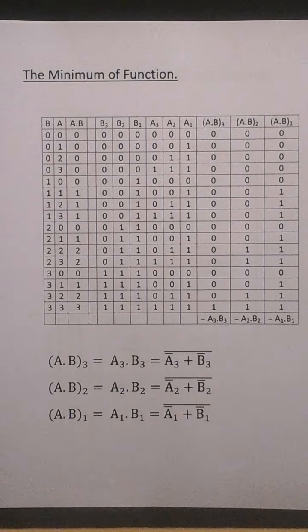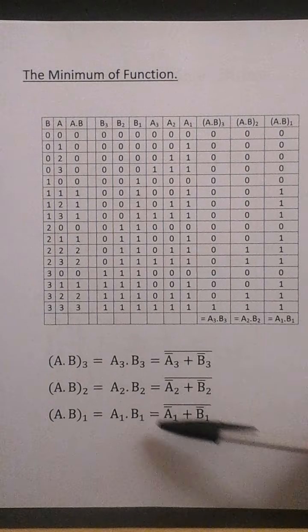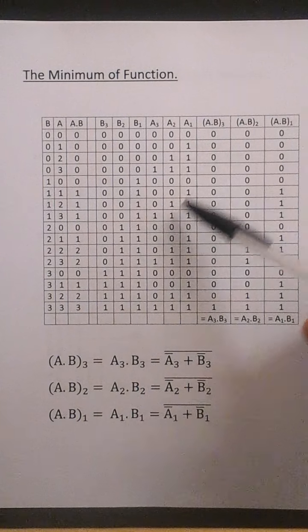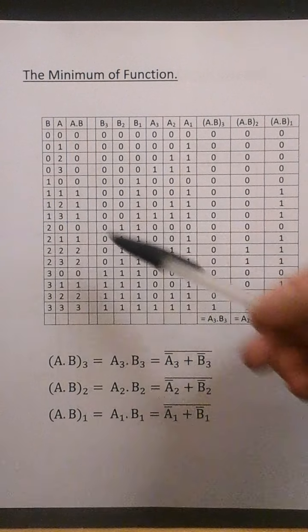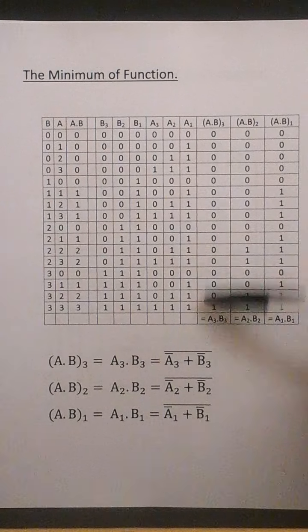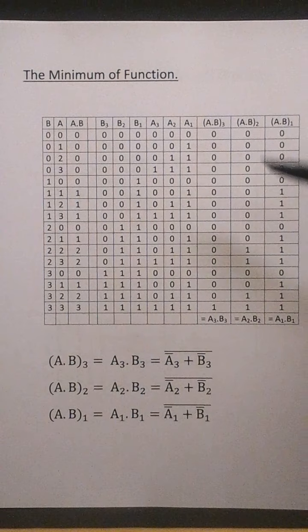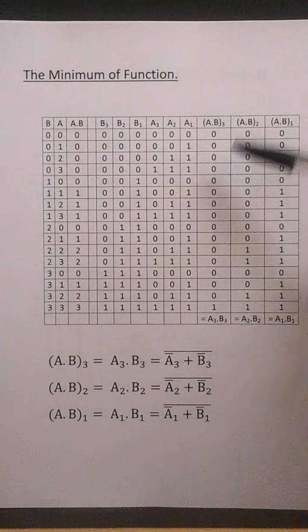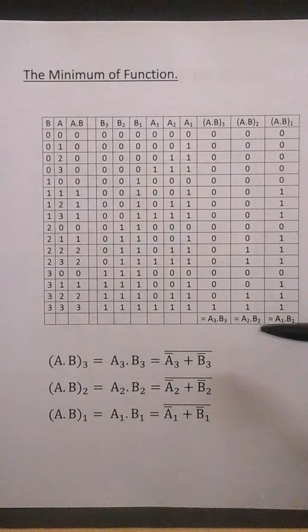So I can get away with using a single chip which contains 6 Schmitt triggers. This would require you to draw a 6-variable Karnaugh map to derive the 3 outputs there. I haven't done that, I've just noticed the relationship between the output and the input.